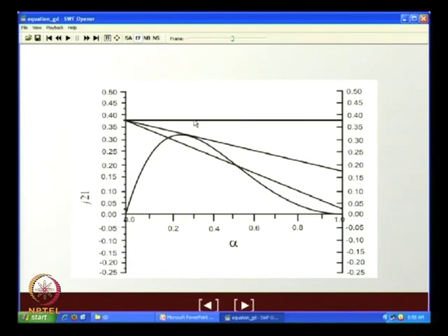So, beyond that, if we increase either of the flow rates, we find that there is no point of intersection between the straight line and the curve. And it is quite expected that beyond the flooding point, there is no stable operation. Either there will be a change in the flow pattern, due to which this curve is going to change, or there will be some amount of rejection of material from the flow passage. Whatever it is, the flow is not going to be stable, and it is not going to retain the same interfacial characteristics as it had retained earlier.